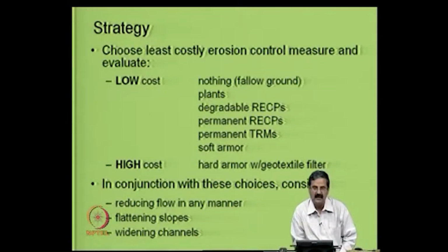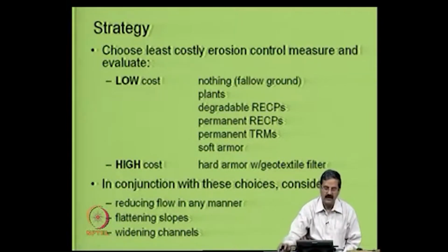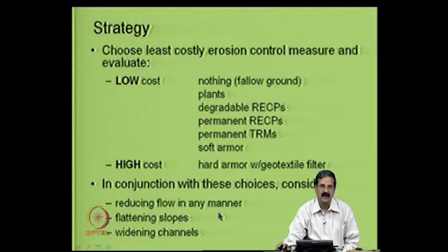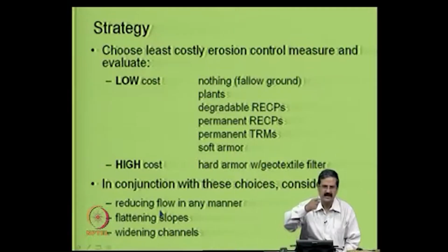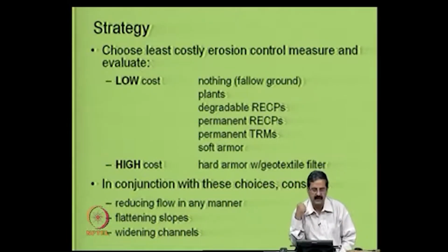Some of the concepts that we should think of is, for example, if there is a water flow, how to reduce the velocity of the flow in the area. Of course, it is not possible in some cases because it is site dependent, but if it is possible, it can be done. Sometimes you must have seen erosion in the form of rivulets, which turns and cuts the toes of the materials. That is quite difficult, so there should be a way of energy dissipation mechanisms.